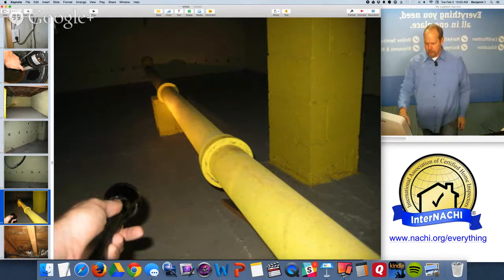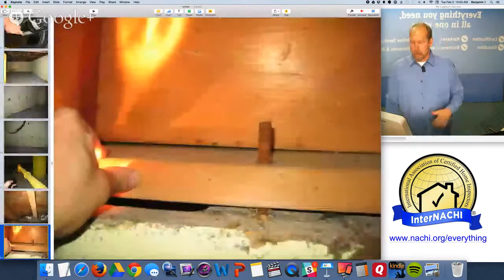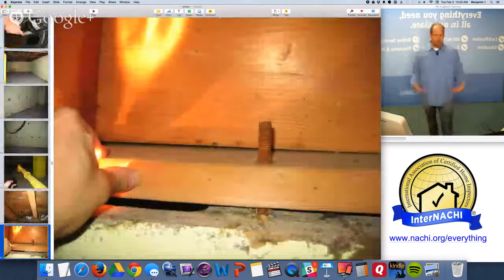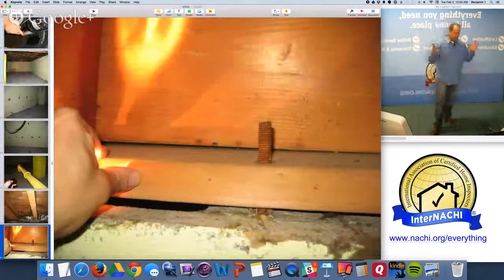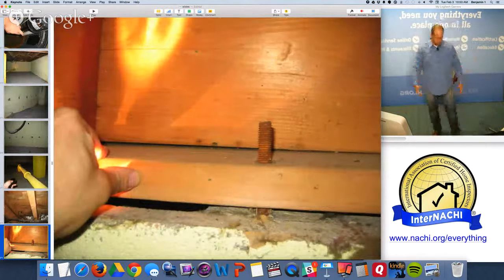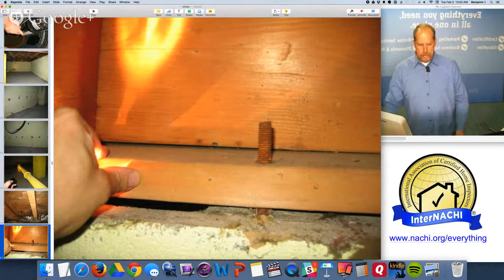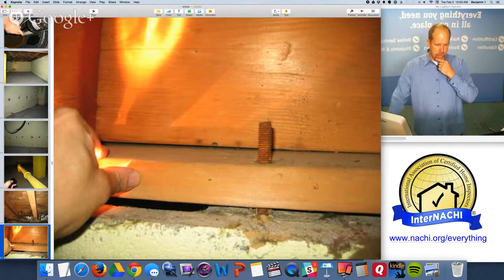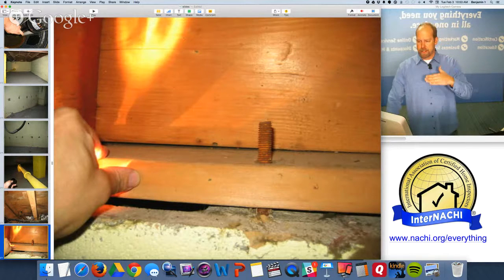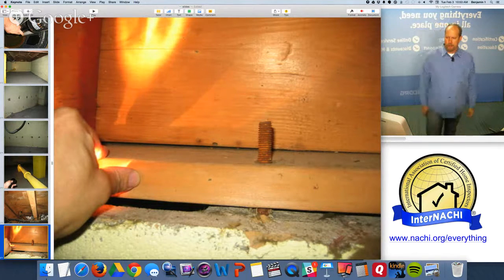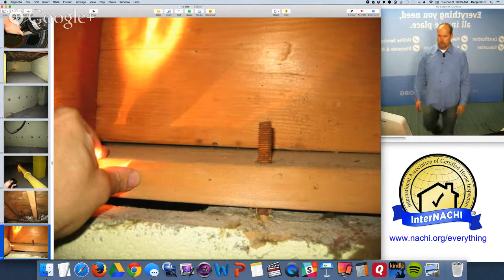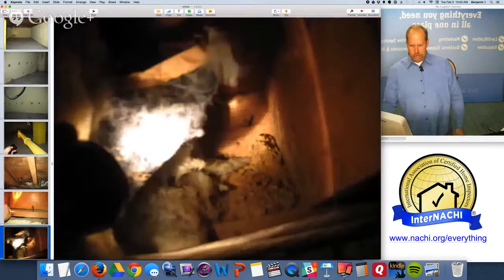And I like to get in there. I have a crawl space suit. I don't do the Tyvek stuff. Looks like some kind of nuclear laboratory. So I use canvas, neutral gray canvas with zippers. And actually, I take a look at how the sill plate is fastened to the foundation, and there's a missing washer and nut at the lag bolt there.